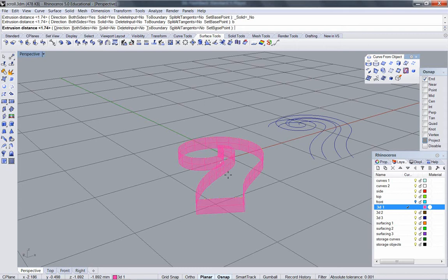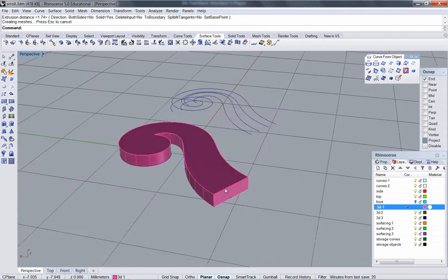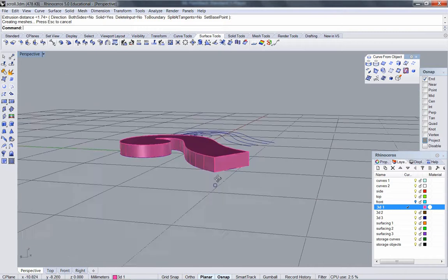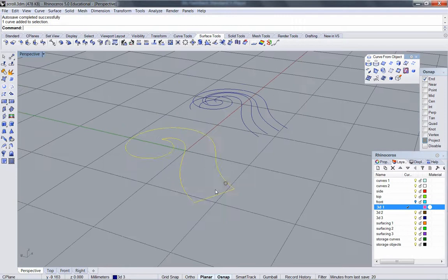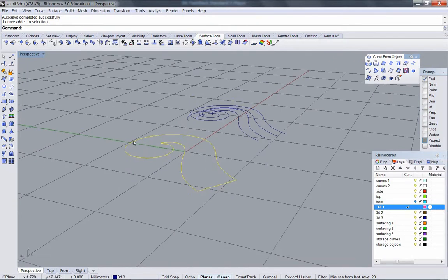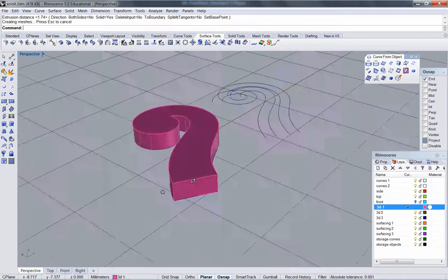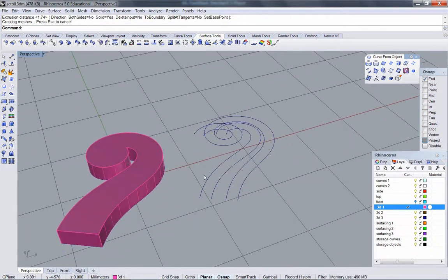Turn off both sides. Okay, so that if I did a fillet, it's going to reach as far down the side as it does over. If I set it thinner than 1.74, the fillet wouldn't be able to have enough room and it would fail. That's actually a little too low for the scroll I had in mind anyway, but it's good to know what that distance is because that's the minimum you can extrude. I'm picturing a scroll more along those lines, okay? So I've got my scroll.